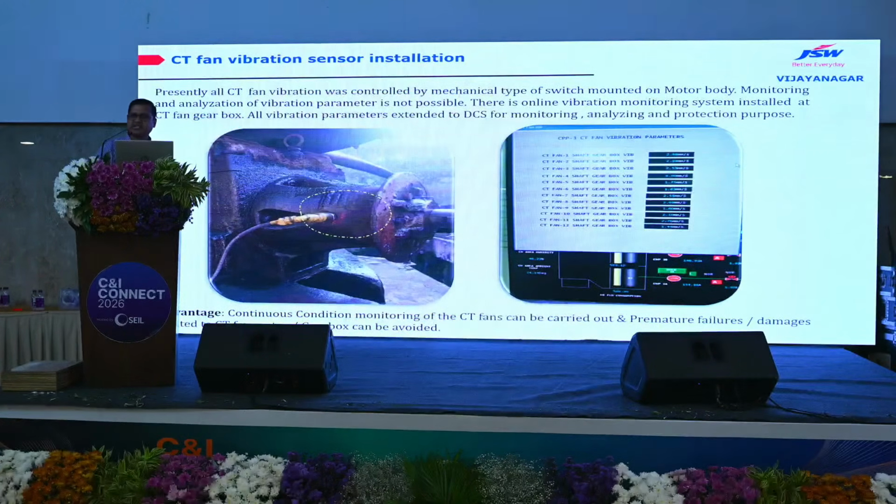And in the fan vibration system, the OEM supplied only the mechanical type motor vibration, but on the fan side and gearbox side, a vibration sensor was not given. So we have initiated installing sensors on both the gear and motor sides, and they are hooked up to this signal. This is for monitoring purposes.